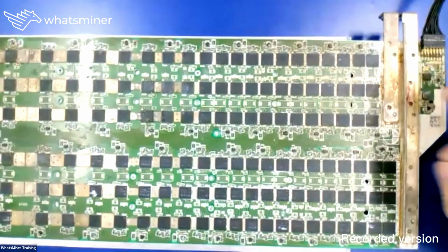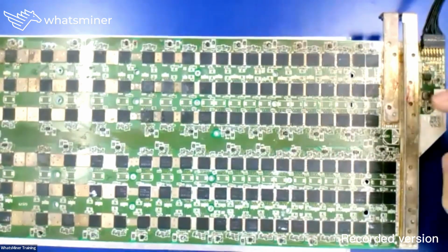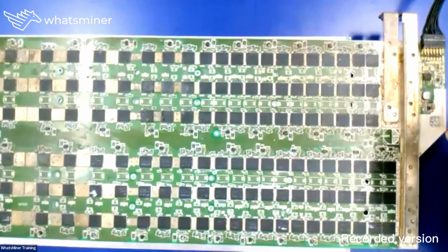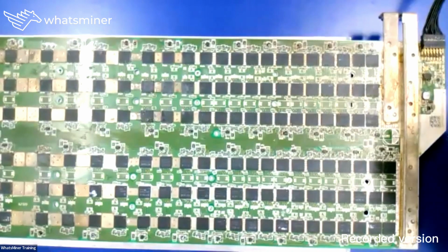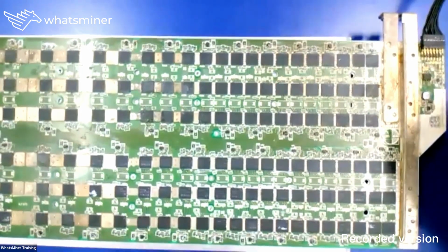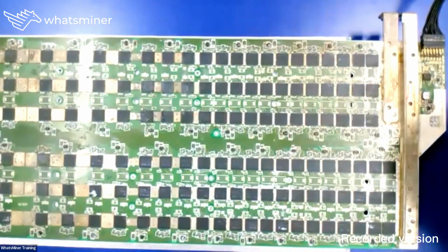After you check the voltage of chip globes and the LDOs, then you can start to measure the 4 signals on the board. Still the same 4 signals. One is RST, second is CLK, third is RXD, and the fourth is TXD. You can measure and repair the 4 signals one by one.